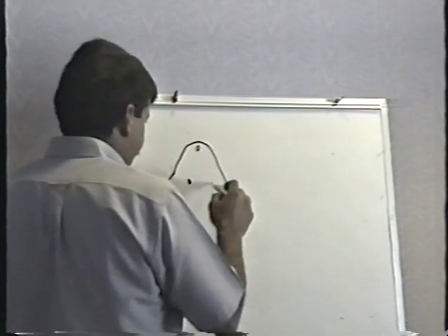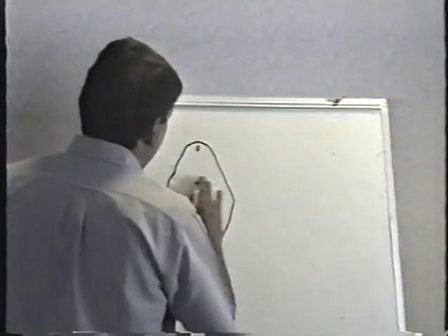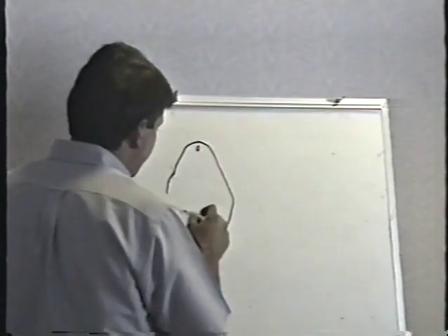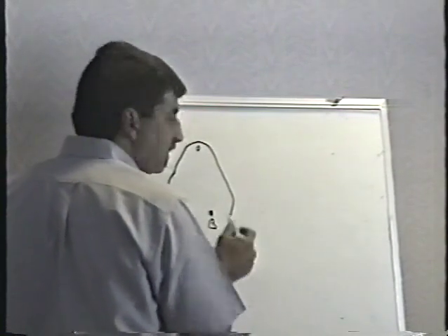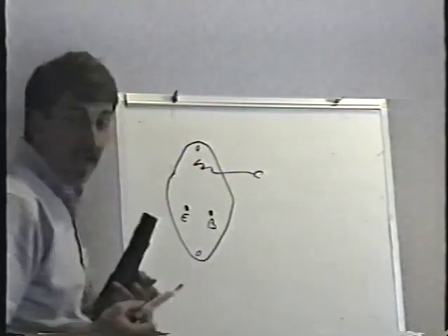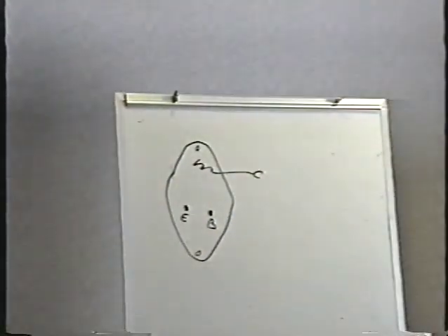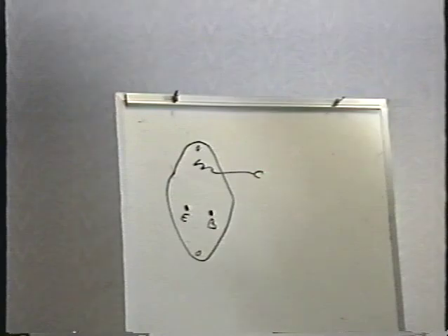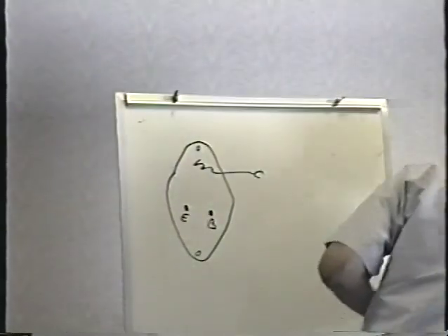These leads, if you hold it right side up so you can actually see on these particular transistors, the little leads there, the one on the left is the emitter and the one on the right is the base, right? The collector is the case of the transistor. The metal case of this transistor is the collector. For that reason, whenever you see one of these transistors mounted on the side of a chassis or on a metal heat sink, and we'll talk more about heat sinks.